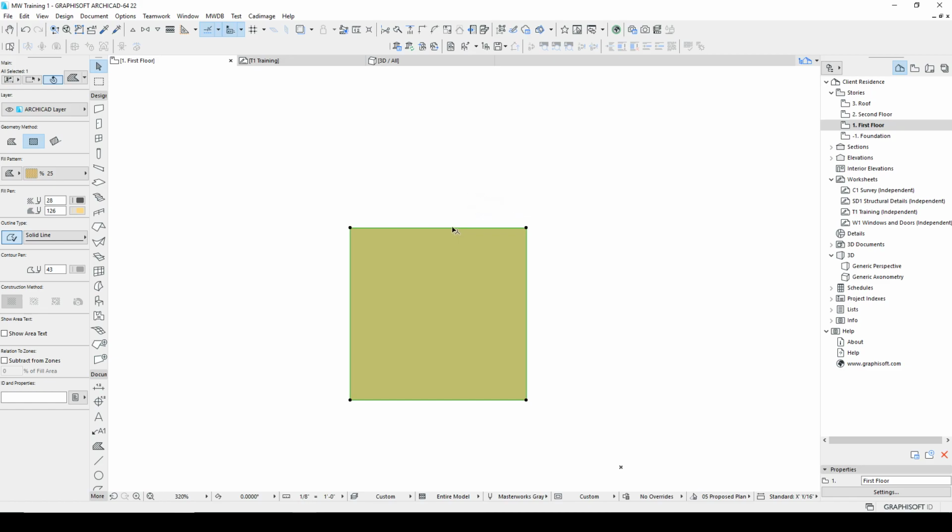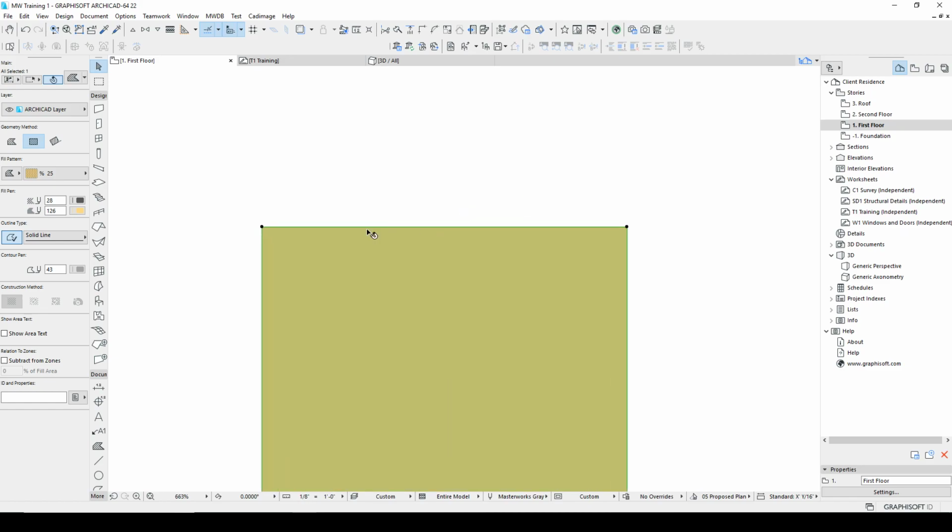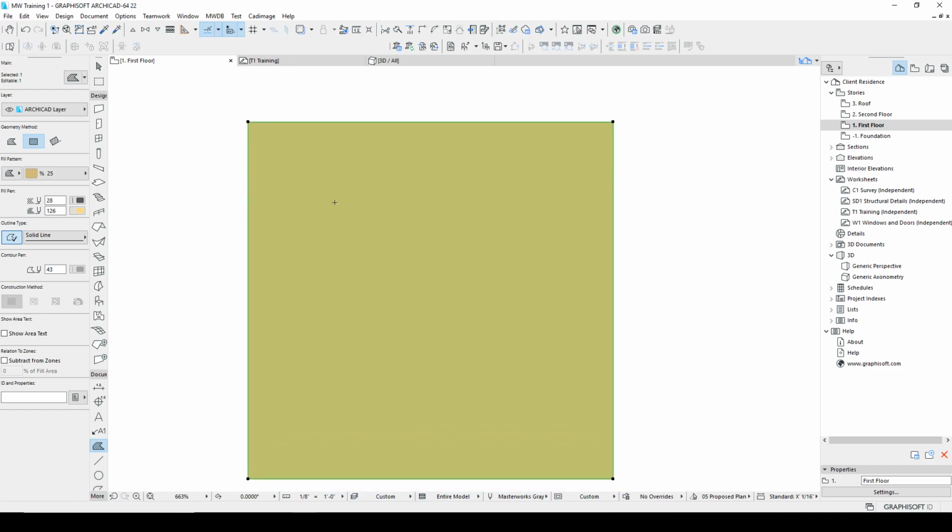Now, if I want to put a hole in a shape, I have two choices. The first one is to select the shape, go to the fill tool, which is Shift L. And the reason I did Shift L, it's like the line is one-dimensional, you hit Shift, and then the idea is that it's a super line. It's two dimensions. It makes sense to me. The real reason is F is fillet, and that one I use a lot more.